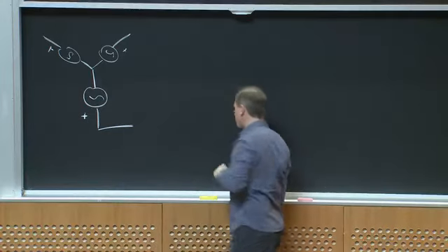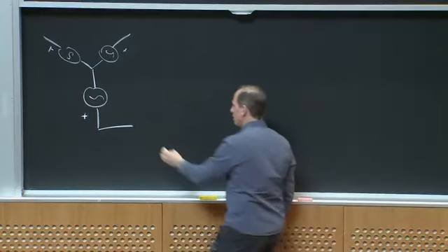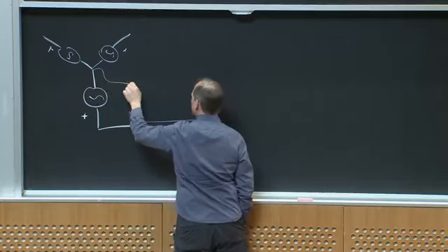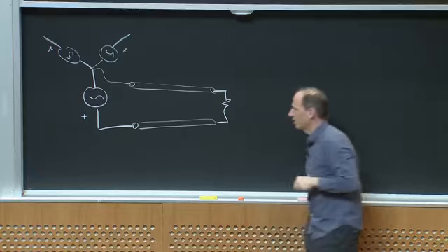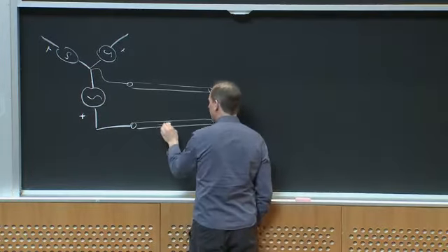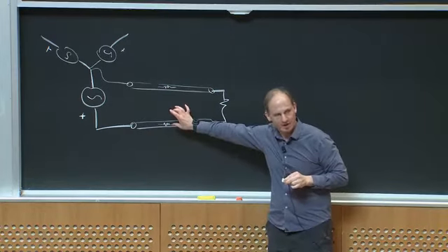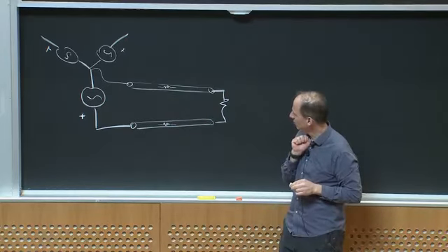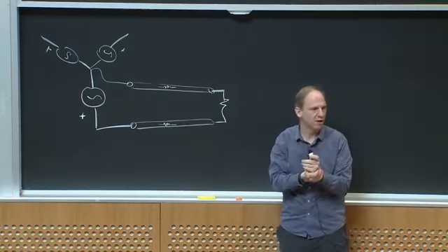And now suppose I wanted to send this single phase. Here's my wires. Here's my first wire. And I'll hook my load here. All right? And keep in mind these wires have some resistance to them, right? So if I want to keep my loss down, I need to use a certain size of wire to carry the current that I want to carry. So that's the single phase system right there. I got to buy so much copper to deliver the power within an allowed loss limit.